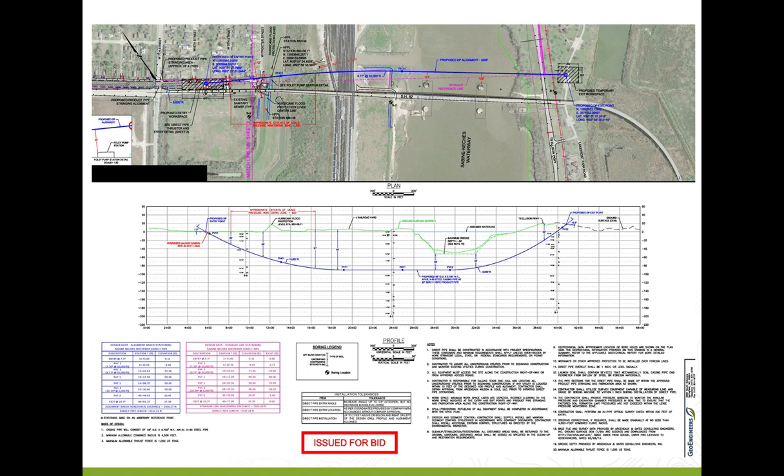So this is a 3,500 foot, 48-inch crossing. The curvature on the crossing is 6,000 to 10,000 foot radiuses, and there is some combined curvature in there. We had to put combined curvature in there to avoid the navigation bollards in the Sabine-Neches waterway, which is the big waterway on the right side of the crossing. That's the third heaviest trafficked waterway in the U.S. And so we're crossing that.